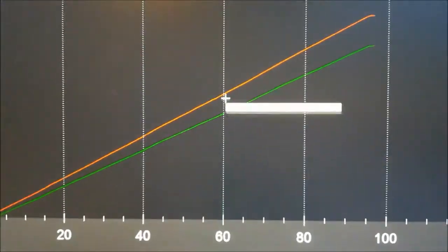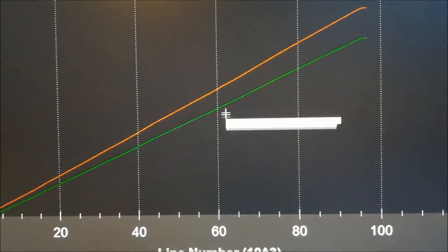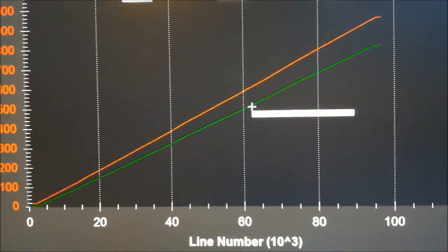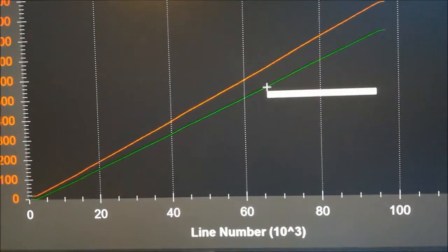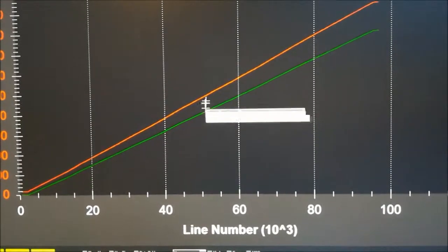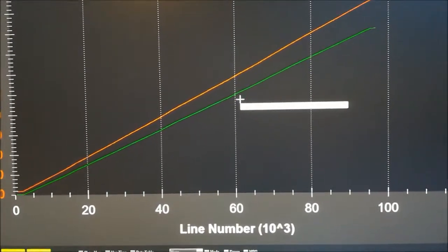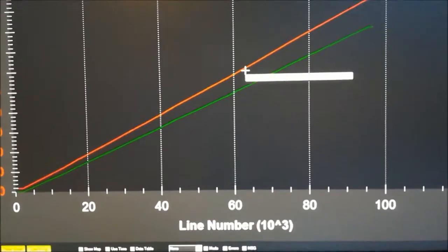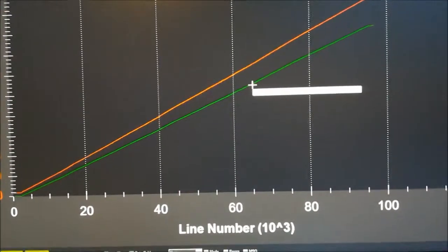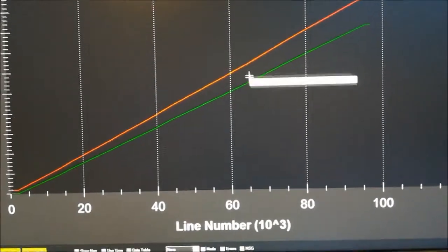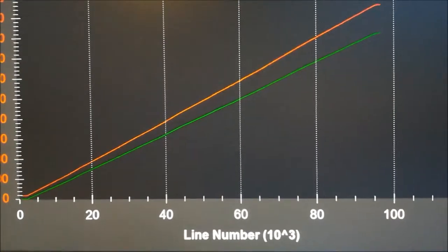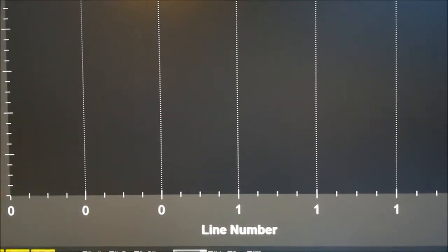Now what's also interesting to look at are the consumed charges. The red one is what the power brick calculated, the green one is what this ESC telemetry calculated. One thing you can note is that it's of course off because the ESCs do not see all the power consumed, but it's not too bad. If you just added a constant value to the current, you probably would get a relatively close agreement. Which means that if one wanted to, one doesn't need a power brick, one actually could use this ESC telemetry as a battery monitor. I was actually surprised how well this potentially could work.